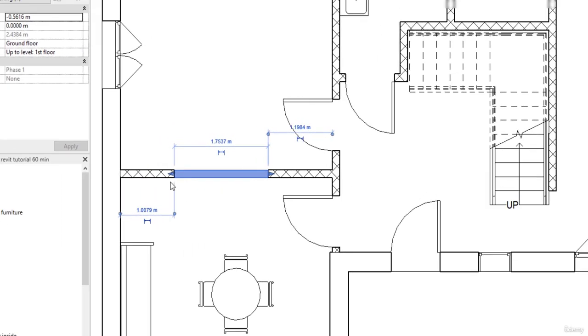How can we place the wall opening at the middle of a room? There is a simple trick for that. In these grips, we can extend or reduce the size of the opening. I click in this one once, and now this length is 0.9. Then I go to the grip at the other side, and I click until I match the first value.